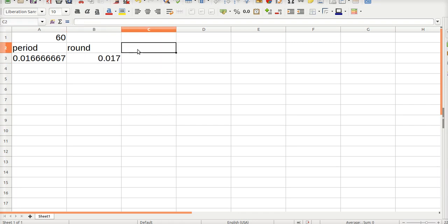And generally when you sample a waveform in Spice or anything really, if you want a good representation of the waveform, you want to sample it 10 times per period, or at 1/10 the period. You want 10 samples per period, or sample at 1/10 the period. So basically all you got to do is move the decimal. So 0.017 is your sample time.